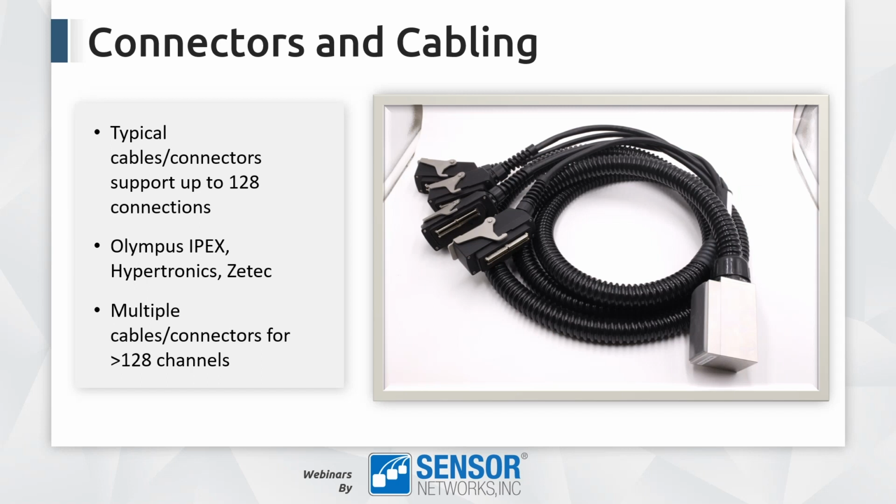And we had to actually use 4 cables and connectors to interconnect that transducer. So generally speaking, as we develop very high channel count arrays, we can get into scenarios where we have to use more and more connectors or custom connectors in order to interconnect the transducer.